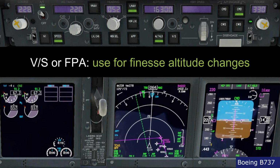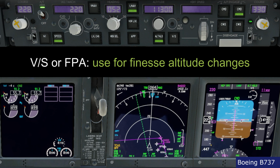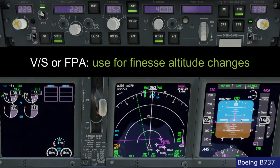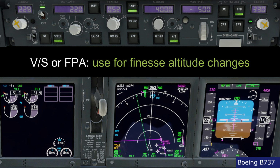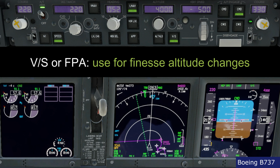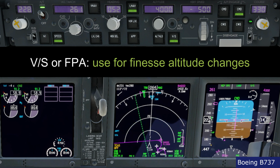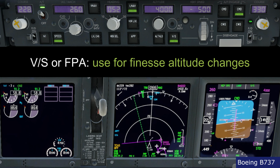Okay, now lower altitude, for the descent I would say there's not much to say. For the descent it is exactly the same condition we saw before. So I click vertical speed, select the rate of descent I want. We say it again, make it a finesse, so no more than 1000 feet per minute, and this will allow you to have controlled speed. Of course, now with this rate I have controlled speed. If I want to accelerate, I will get a bit more thrust and the aircraft accelerates to 260 knots, so it's not a problem.